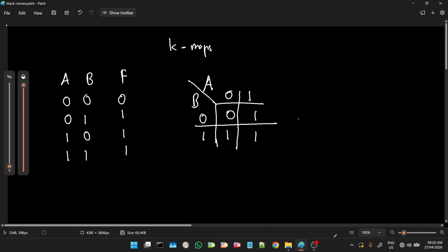So there are some rules that you should follow while using K-maps. First things first, you should only group ones. You should group ones, but you can only do it in multiples of 2, like powers of 2. So it goes 1, 2, 4, 8. I learned this from the OG tutor, JG, the chemistry guy. I will link his videos down below. But simply put, we can select this one and we can select these two, right?